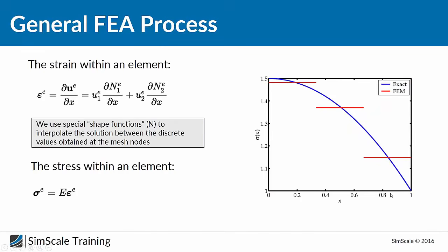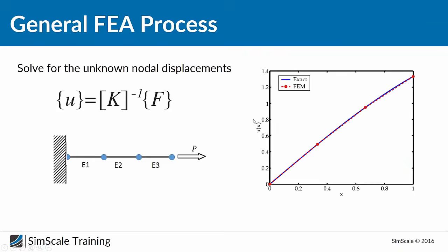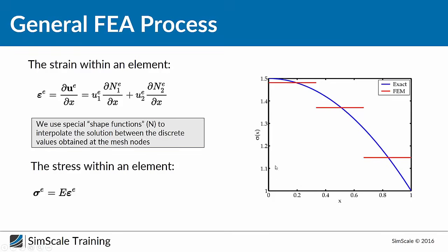And if you take a look at this chart, it's showing the strain instead of the displacement now, which we can calculate out of the displacement. And while the exact solution gives us an analytic function of the strain over the length, the finite element solution will only give us an averaged strain for every element. So, this is the big, let's say, source of errors.